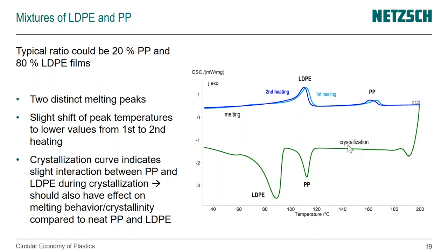But you would have to have some knowledge of molecular weight. You can't get information on that directly. For that, again, molecular weight, there's GPC, gel permeation chromatography, that you can use to really directly measure molecular weight, or you use rheology, rotational rheometry, for example, to study that if you want a dual use piece of equipment.